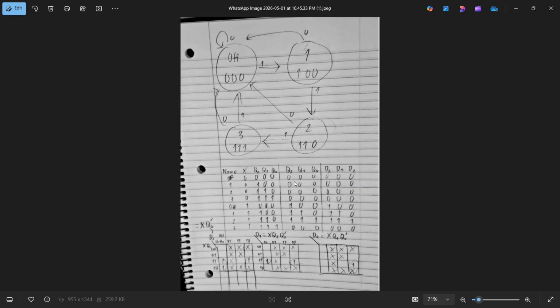We have chosen D flip-flops because they are simpler to implement in Logisim. If I had used JK flip-flops, there would be more equations, but simpler equations, I would say. I also used a Moore machine so that the outputs depend only on the current state. I chose a 3-bit state design so that the outputs can directly drive the LEDs without additional decoding.